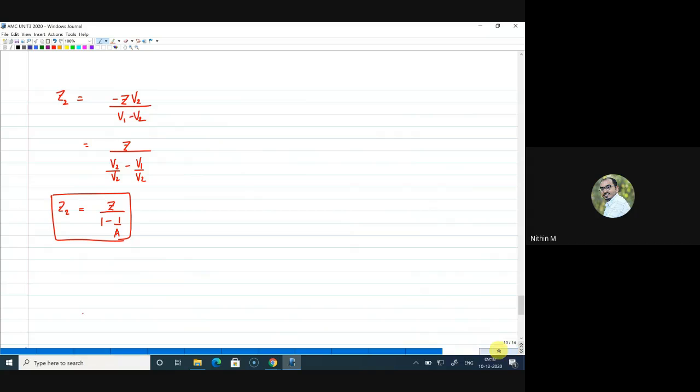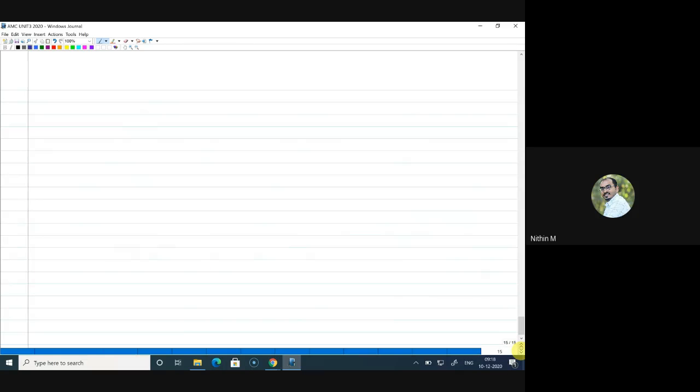So let us understand this by looking at a small example. I am considering an amplifier, say this is an amplifier, having a gain of minus AV. When I mark it as AV, the meaning is that the main signal path is from here to here, through this amplifier block. But there is a capacitance present in the feedback path, and say this capacitor is Cx.